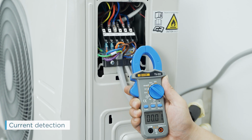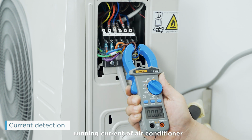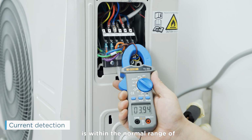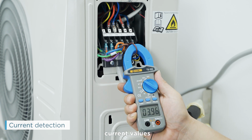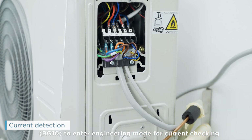Current detection. Use a clamp meter to clamp the live wire to detect whether the running current of the air conditioner is within the normal range of current values. You can also use the remote control RG10 to enter engineering mode for current checking.